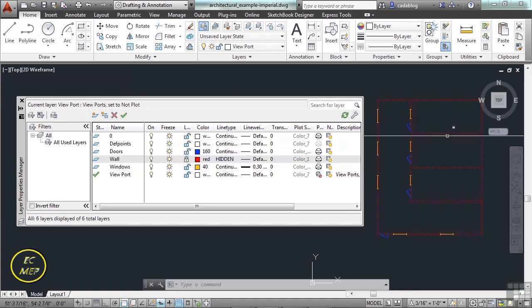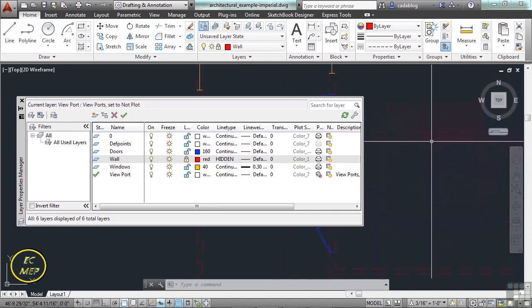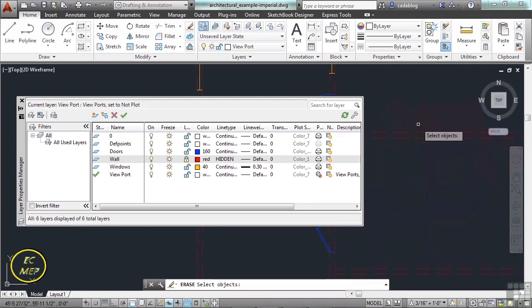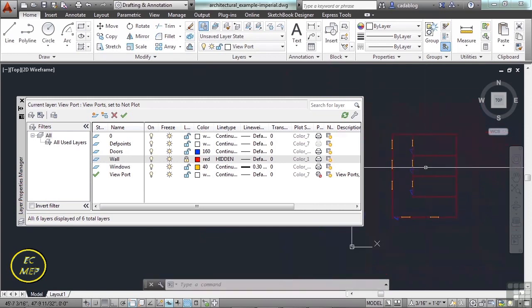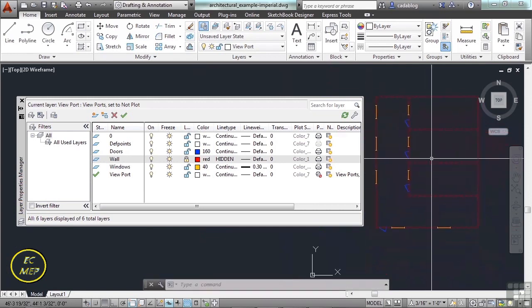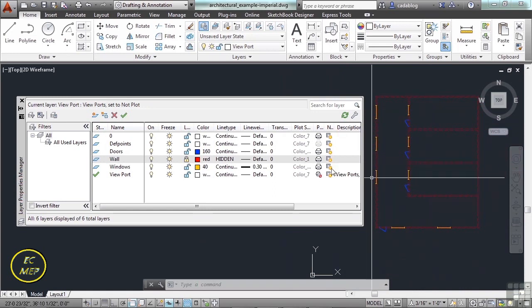And you can see it sort of fades it back. And when you move over that object, it puts a little padlock looking icon. I can select the object, but I can't delete it. It won't let me. I can't change it. I can't do anything to it. So when you have line work that you need to have locked in, then we'll lock it down.